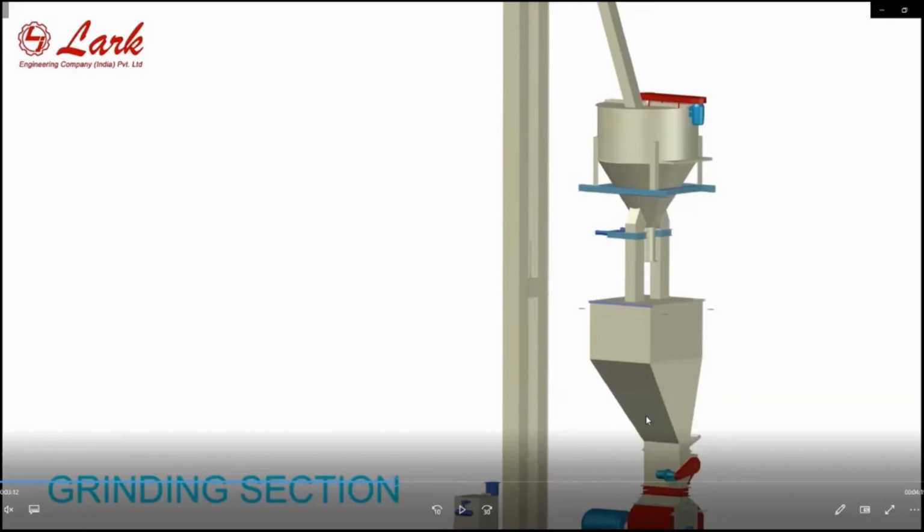To have a good grinding and balance, note that when the grain comes, the load on the hammer mill increases, and when the fiber comes, the load decreases. There may be a pulsating load with respect to grain hardness.